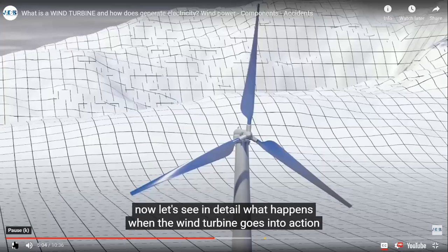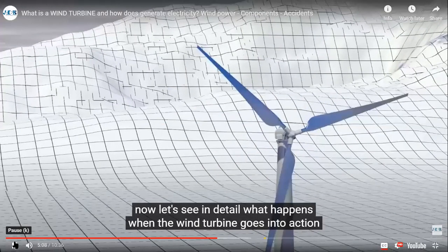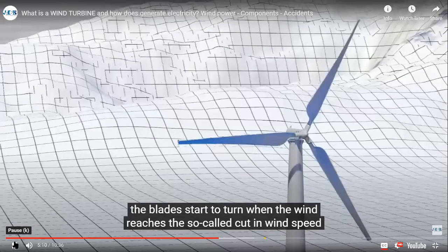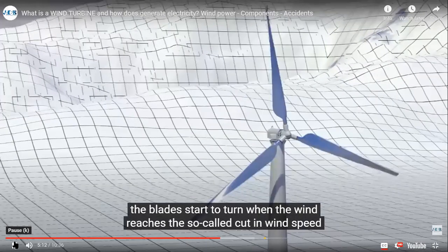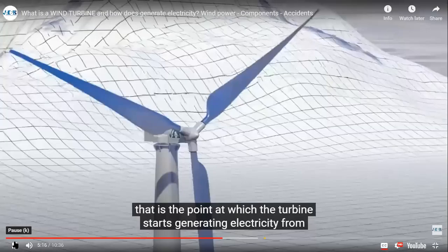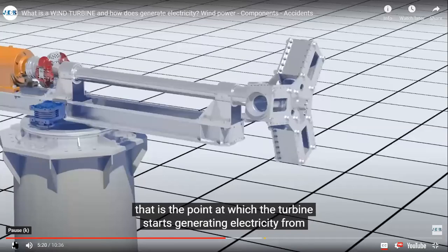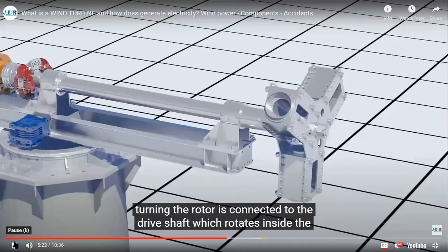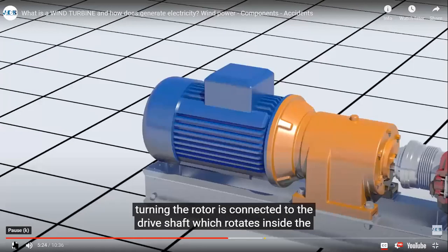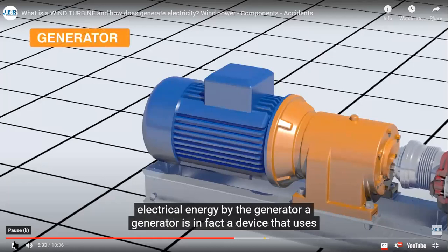But now, let's see in detail what happens when the wind turbine goes into action. The blades start to turn when the wind reaches the so-called cut-in wind speed. That is, the point at which the turbine starts generating electricity from turning. The rotor is connected to the drive shaft, which rotates inside the nacelle. The rotational energy of the drive shaft is transformed into electrical energy by the generator.